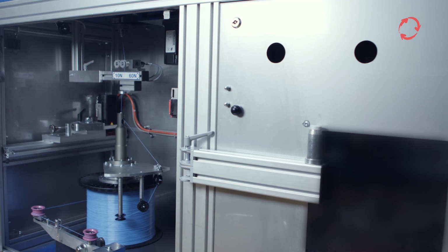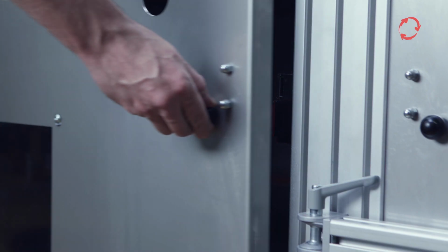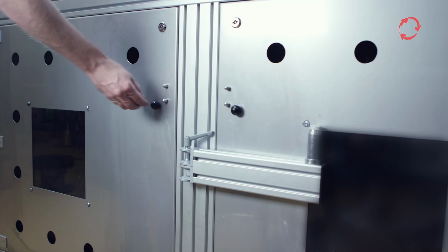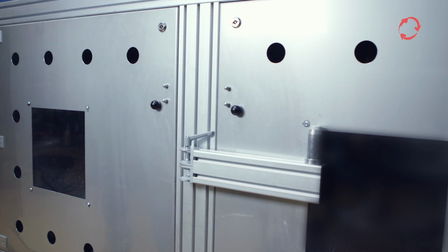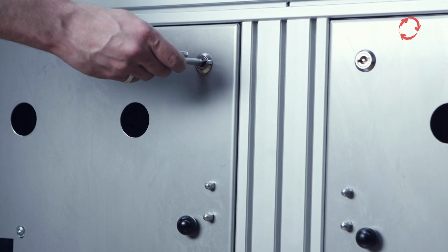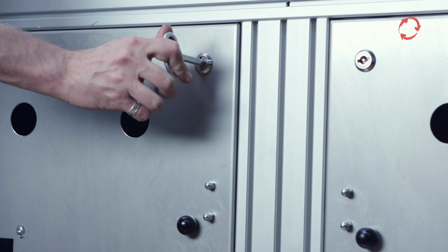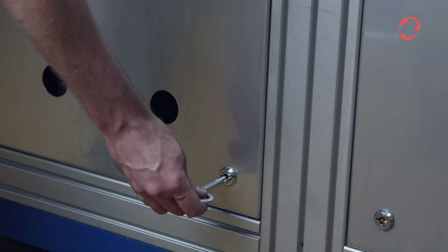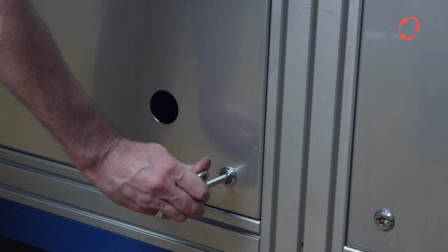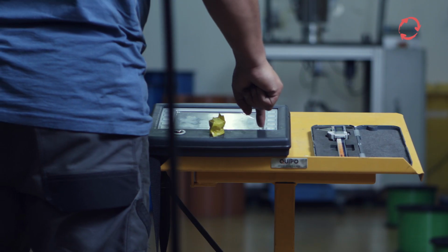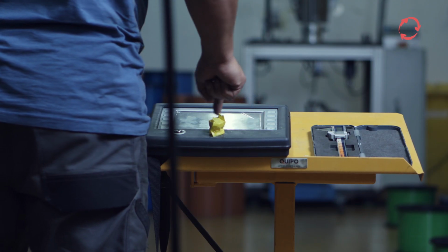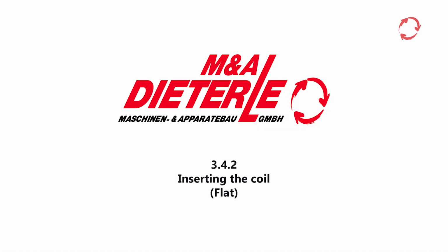After the final inspection, the machine door can be closed and locked by means of a switch cabinet key. Only after correct locking of the door, the process start can take place. The machine itself is now ready for the winding process. Now the manufacturing parameters according to the spiral type and size are set on the controls via the central touchscreen.